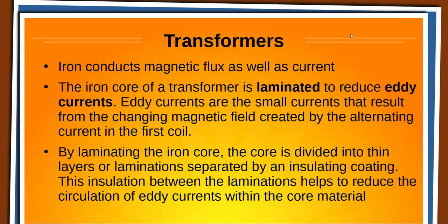Why do they put them in oil for power transformers? The heat. So all the oil does is cool it? Yeah. And it's designed, if you notice, they have those pipes. It's set up so that the heat actually causes it to convect and circulate. So it circulates, and you've got fins on the pipes. There's a lot of power in those big transformers.